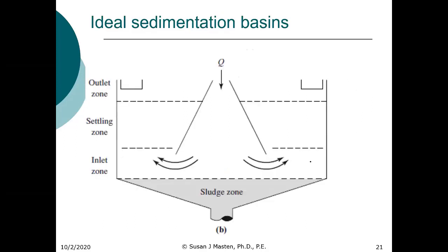We also have upflow clarifiers. Now these operate a little differently. As I mentioned, these have your mixer in the upper portion of the inverted cone. This is where you have the flocculation. So we'll just draw it. Okay. As if we had the paddle wheels. We wouldn't have paddle wheels, but we have typically an impeller flocculator here. So we have flocculation here. And then the settling occurs out in the inverted cone here.